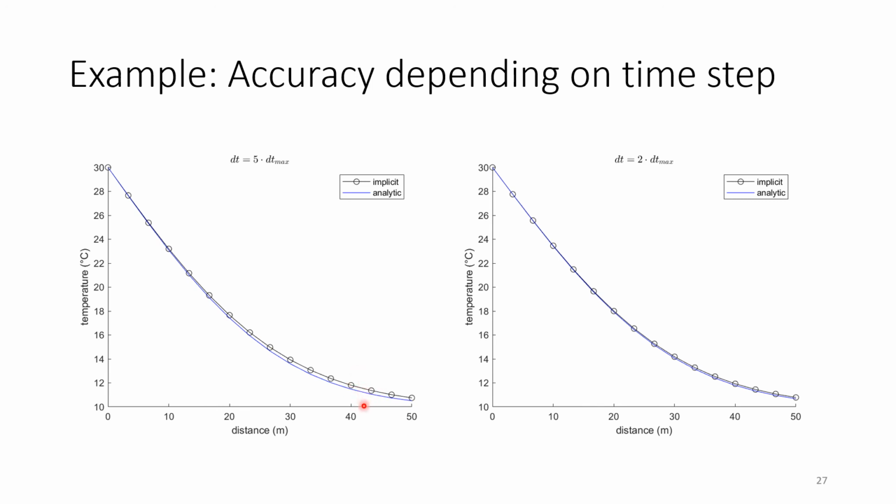So this divergence still matters. And if I decrease the time step further, I will see that the difference between the analytical and implicit solution is decreasing. So this maximum possible time step is still an orientation, also for an implicit solution, with respect to accuracy. So usually, it's not a general rule, but usually the larger the time step is, the more inaccurate your numerical simulation results get.